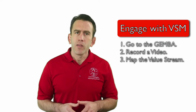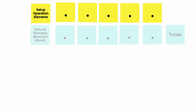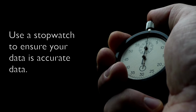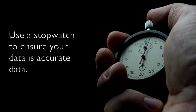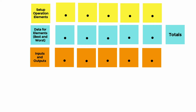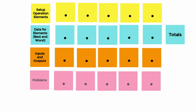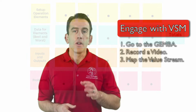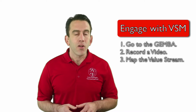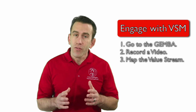A good way to map this is with the process elements on one level. Below your setup elements, you can place the data you captured for the element above. You should use some type of stopwatch or other measuring device if need be to ensure your data is correct. Then, any types of inputs and outputs such as tooling, materials, or information, and finally, one row dedicated to problems you see at that level. At the very least, be sure to capture the top level or setup elements. This value stream can be adjusted for more accuracy when you watch a recording if you need to.